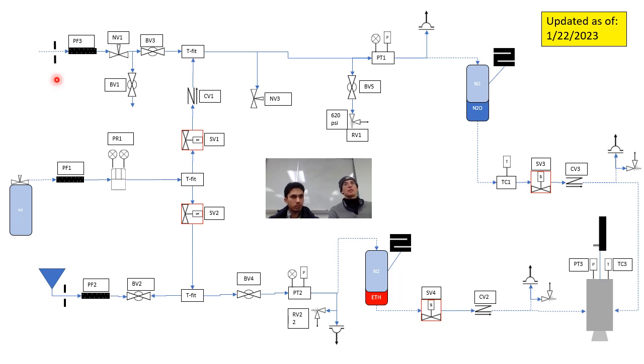The reason for a purge process is because nitrous oxide is an oxidizer, which is one of the 3 key elements for fire. It's oxidizer, fuel, and spark. We have plenty of oxidizer once this thing is filled. Nitrous oxide should be treated just like liquid oxygen, gaseous oxygen. It's dangerous, and so we want to make sure there's no fuel, because that limits the amount of stuff that can burn if a spark happens.